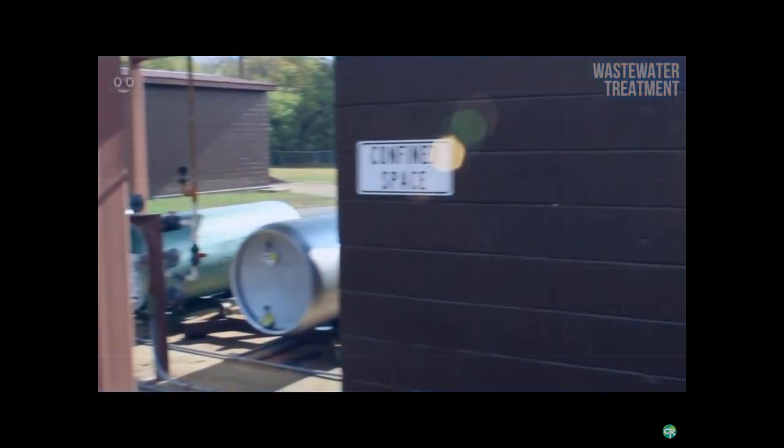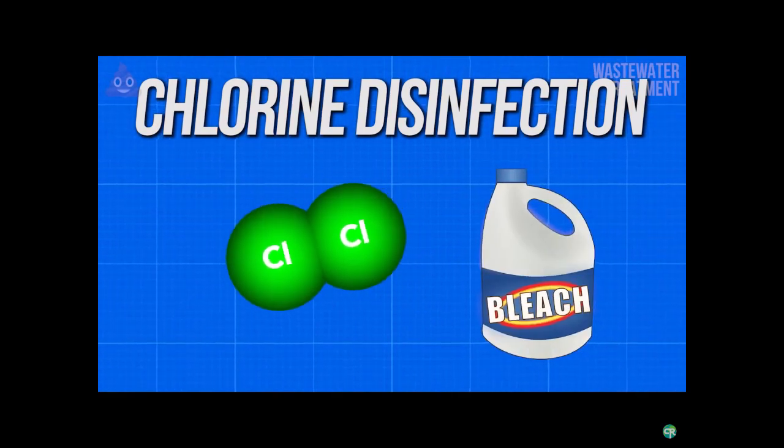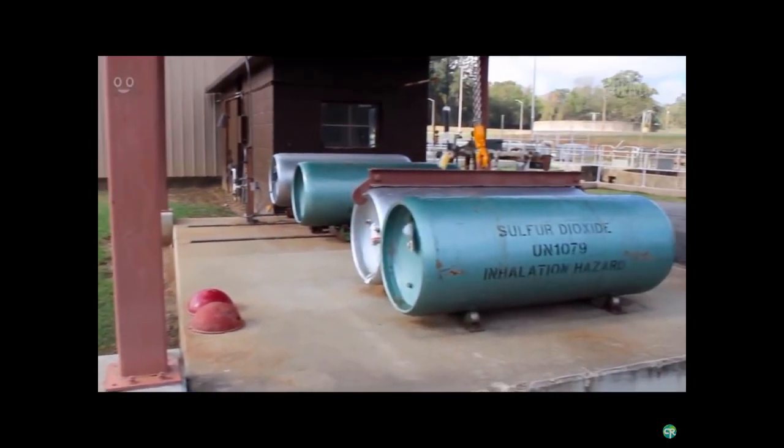Chlorine disinfects the water through chemical disinfection. Chlorine, which you can think of as concentrated bleach, is added to the effluent here to kill off any remaining bacteria and organisms still living in the water. When chlorine is added to kill off the bacteria, it then has to be removed before it can be discharged, as to not kill off anything in the discharge location.